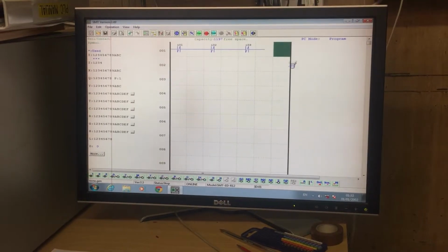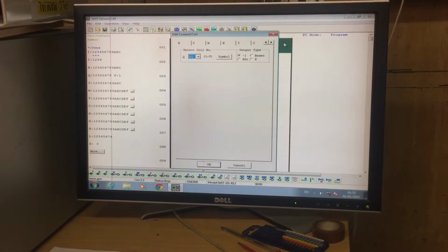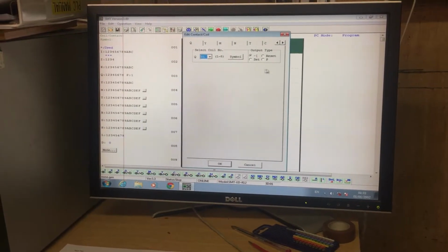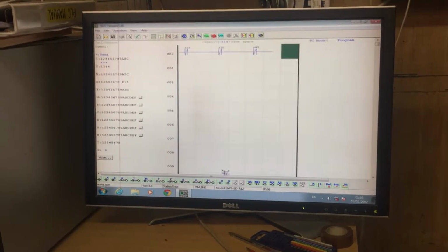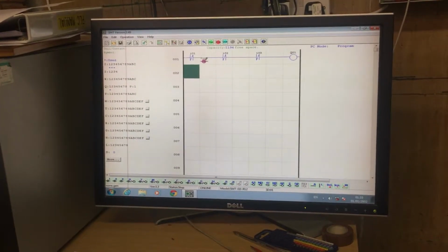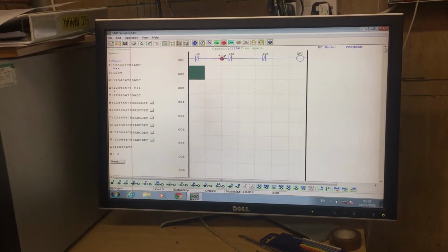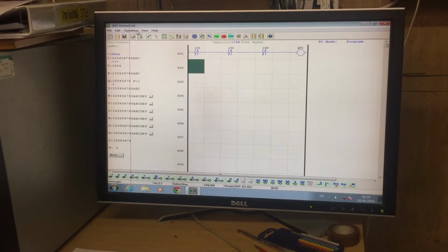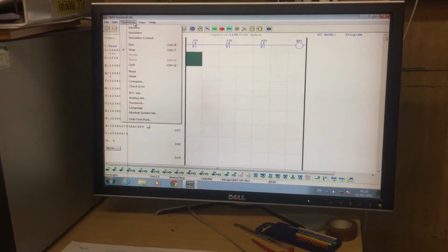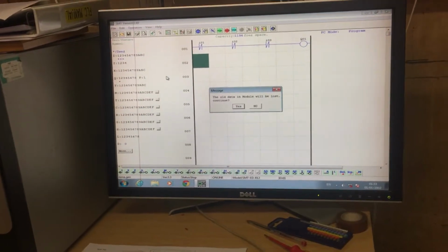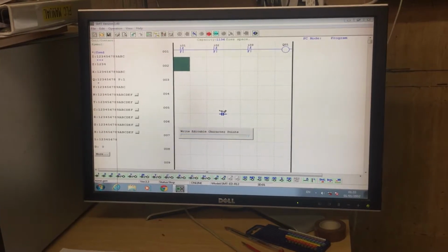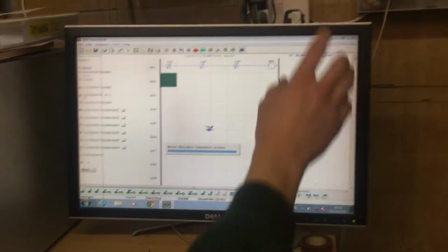So you click on Q, and this goes after the inputs here at the end. Select where you want it to go: Q1, which we've connected in output 1, and it's a normal output type. After the NAND circuit is complete, it then needs to be written to the PLC. This is done by Operation, Write and Yes, and this writes the program that we put here onto the PLC, and then it saves to the PLC.